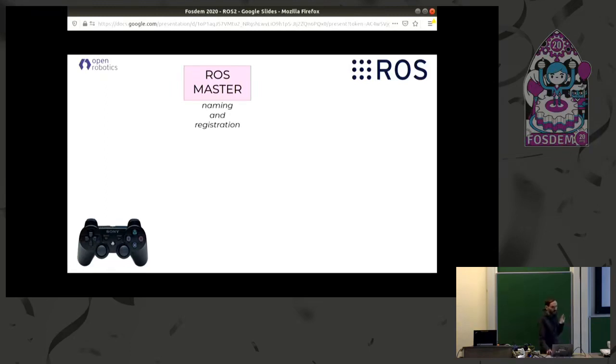So how the remote control is going to be inside ROS. I'm going to just run a part of the package, which is this blue bubble. There is a standard POSIX process, which is going to control the remote control. And it's going to publish a communication channel, just bringing all the keystrokes and information from the remote control into ROS via that communication channel, right?